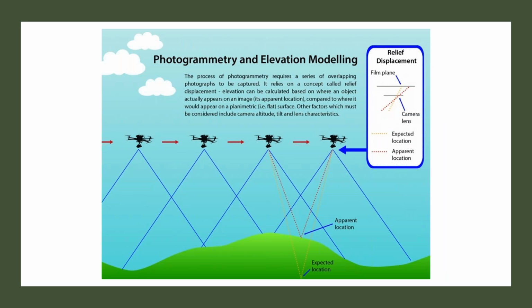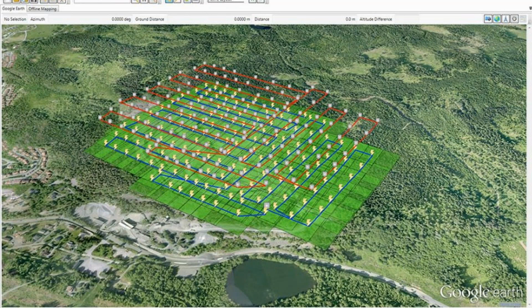For those not familiar, this is photogrammetry. It gets confused sometimes just because the data we are producing is a point cloud, so people think it's laser scanning, and it's not. It's using photos to create three-dimensional data. How we do that is we set up our UAV to fly a pattern with a certain amount of overlap. And the 3Dsurvey software is able to take these photos and calculate three-dimensional points from the pixels on the photos. It is pretty amazing technology.